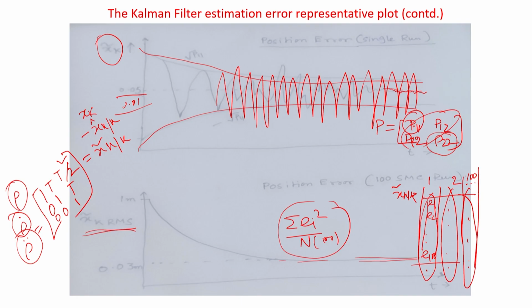But if it is a constant velocity car, then you should use a lower Q, which means you want to give trust to your model. If I increase Q, that means I do not trust the model, and I will trust my measurement process.